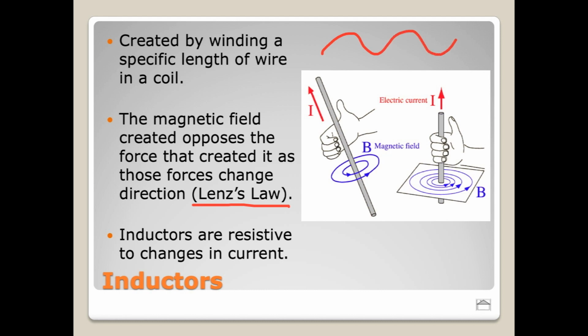So when we increase our voltage here, the magnetic field rises to follow it, and then as soon as we reverse to the negative here, we still have a positive magnetic field that is kind of lagging behind, and that positive here fights this stuff down here. And so we have this kind of push and pull relationship between the electricity and the magnetism.